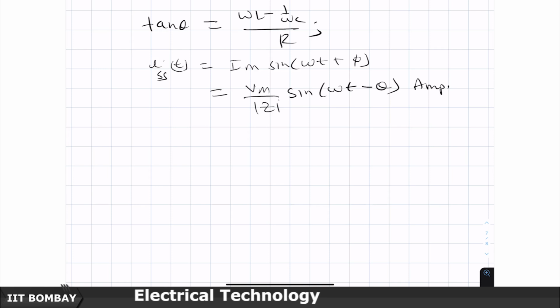Similarly, here the net effect of R, L and C, which is an impedance, is impeding the flow of current, hence impedance, and the reciprocal of impedance is called admittance. The current is also a sinusoid, scaled by the peak voltage amplitude divided by the impedance and shifted by an angle theta. So every time we do not need to solve an integral differential equation, please.